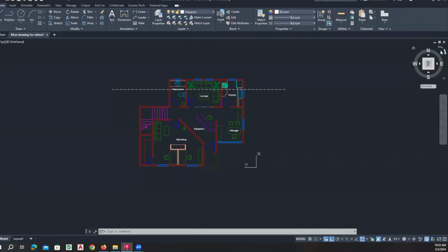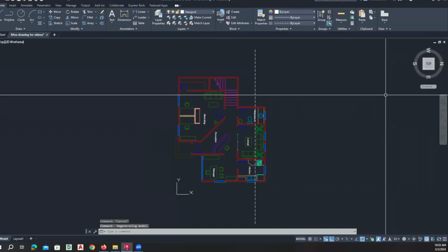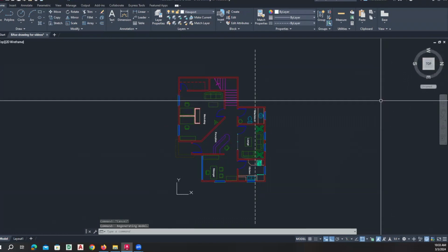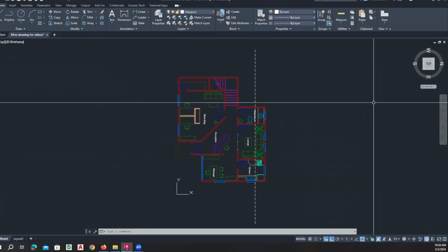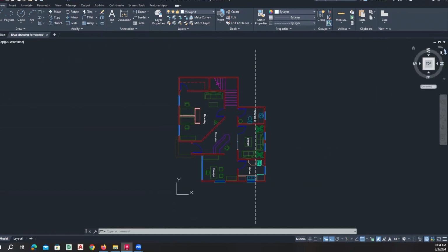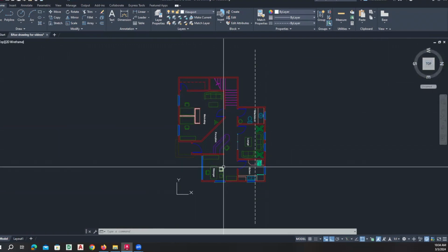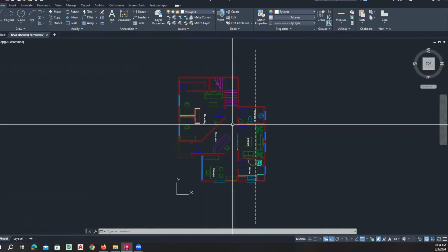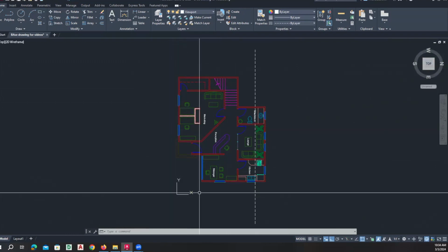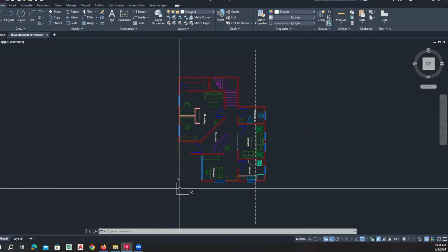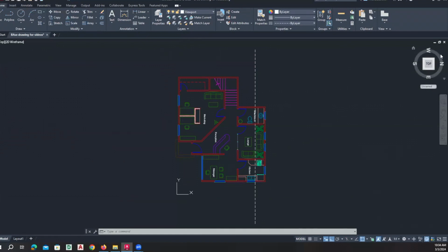And what that allows us to do is actually rotate the views so that we can basically navigate around our plan in 90-degree increments. Clicking on that arrow once, it rotates it 90 degrees, thereby making my view parallel to the current UCS, which puts the x-axis along the bottom pointing to the right and the vertical y-axis pointing up. Okay, so if I were to go back to that arrow again, I can rotate it again.